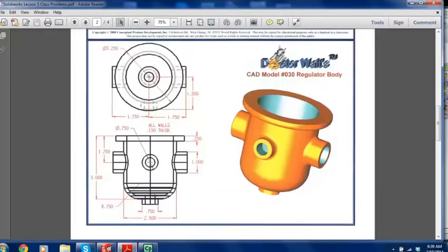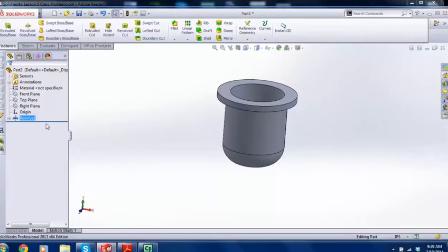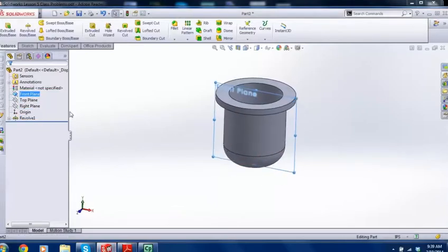Now let's have a look. Let's get this first port on the right hand side. Okay, so let's look at the front plane. We call that the front plane. And let's look at the top and the right. Okay, I need to draw a port here on the right hand side, and I need to extrude it up to the surface.